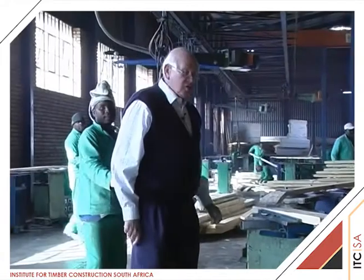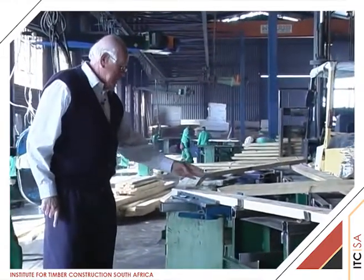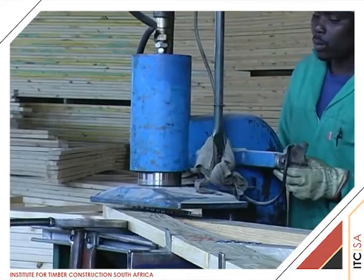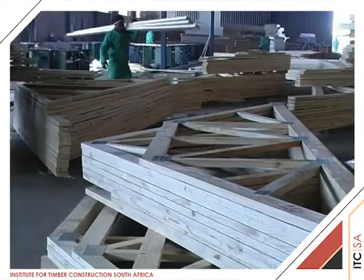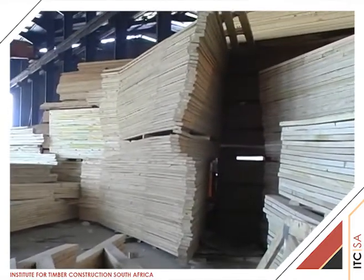The timber which has been cut to the correct angles and length is then placed into jigging machines. The designed nail plates are placed over the joints and are then pressed into position. Once the trusses have been completed, they are removed and placed on the stack and ready to be delivered to the site.